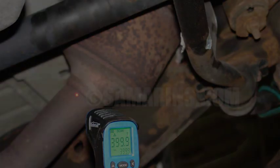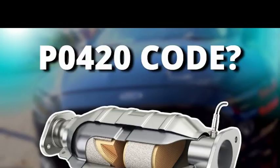To diagnose the P0420 code, a mechanic will need to use a scan tool to retrieve the code from the car's computer. They will also need to inspect the catalytic converter and the oxygen sensors to look for any signs of damage or wear. If the mechanic suspects an exhaust leak, they will need to use a smoke machine to find the leak. Once the mechanic has diagnosed the problem, they will need to repair or replace the faulty component. In some cases, the catalytic converter may need to be replaced.